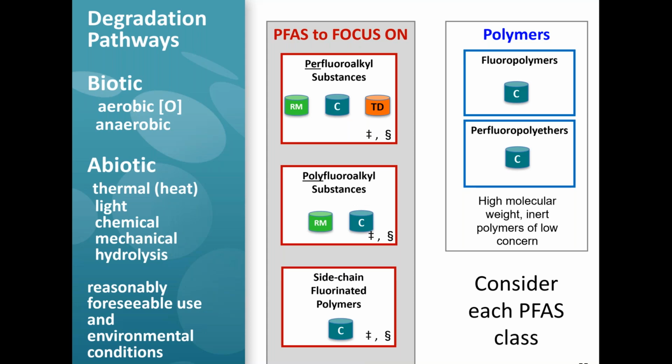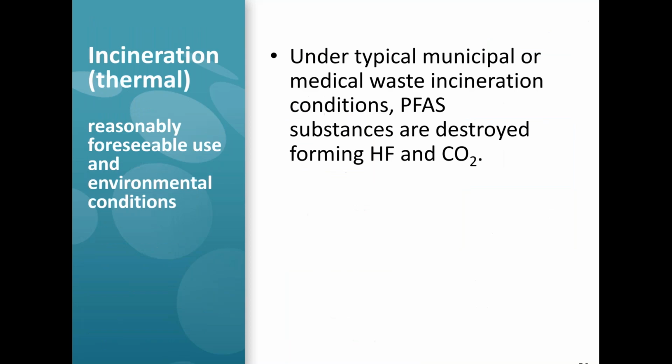Okay, so I'm going to take on abiotic degradation by thermal means first. Next slide, please. So what I believe we know scientifically about thermal degradation of per- and polyfluoroalkyl substances is that under typical municipal or medical waste incineration conditions that are regulated and specified around the world, PFAS substances are destroyed to form HF and CO2.